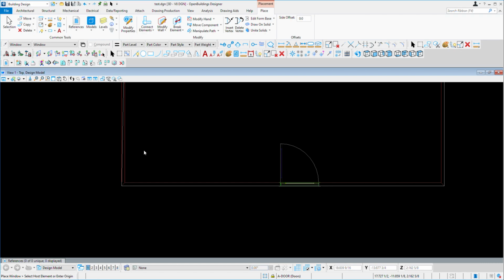Every window has some base offset. Our wall height is about 5 meters, so we need to set the base offset here. The base offset will be around 2 meters or 1.5 meters, and the dimension of the frame we can change: a 2 meter window, and the height of the window I also need 2 meter. You can change whatever you want.